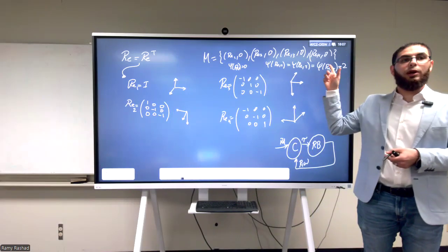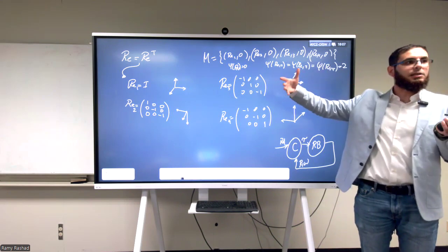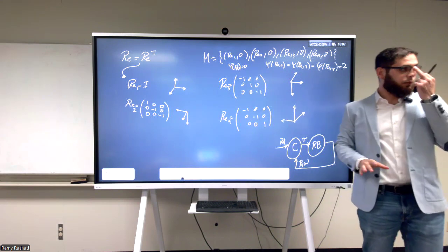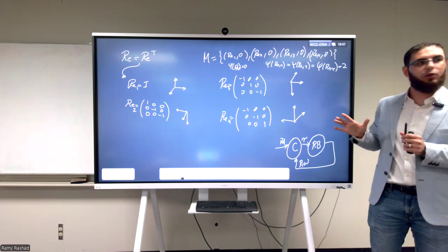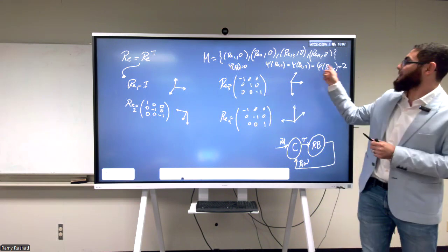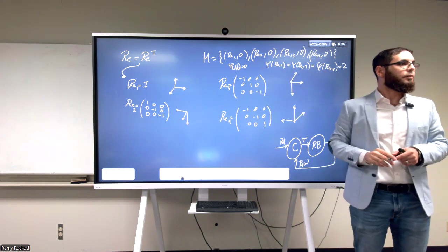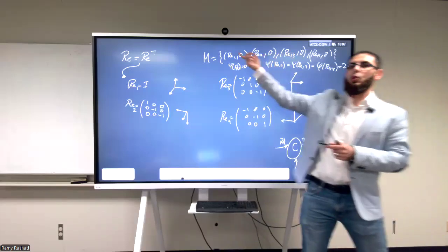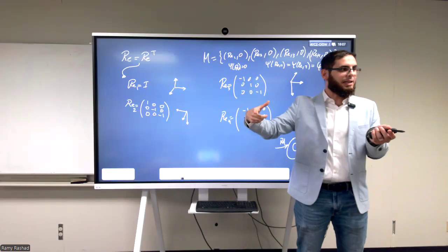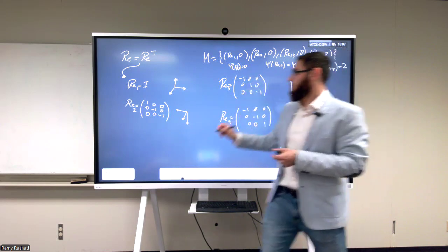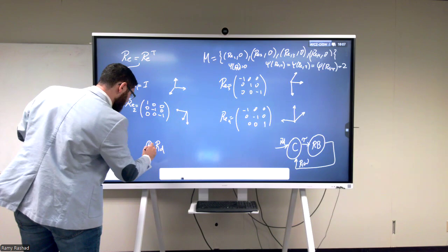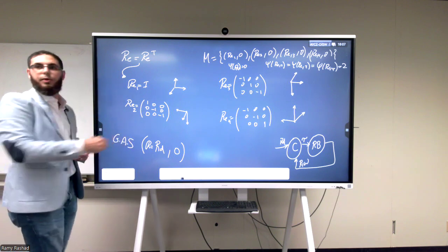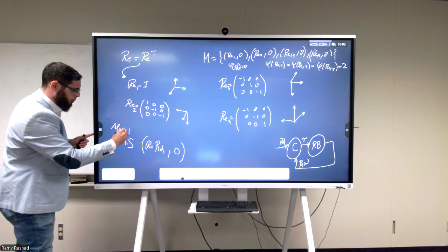These 3 points that are removed from the state space are actually equilibrium points of the system, and they are the only other equilibrium points. You can show this, but this is extra stuff. This is some stuff that you can find in the literature. I can point you to it if you're interested: this control law at these 3 points is actually unstable. So for the closed loop system, I have 4 equilibrium points. 3 of them are unstable, and for this one inside of this set, I can show that it's asymptotically stable. So this is equivalent to showing that R equal to R_D, and 0, is a globally asymptotically stable equilibrium point, but it's almost globally asymptotically stable.